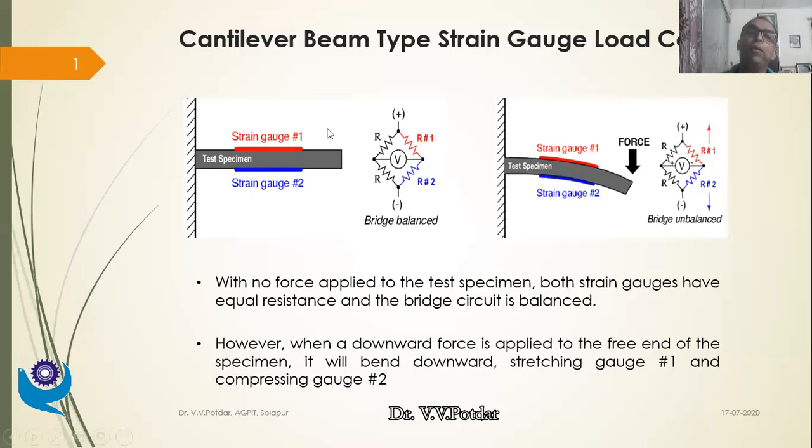So the bending stress sigma B will be equal to M by Z. So Newton millimeter divided by millimeter cubed. And what do I get? Ultimately the units will be, bending stress sigma B will be equal to M by Z, Newton per millimeter square. Isn't it? Now we have got the stresses induced in this rectangular cross-sectional cantilever beam.